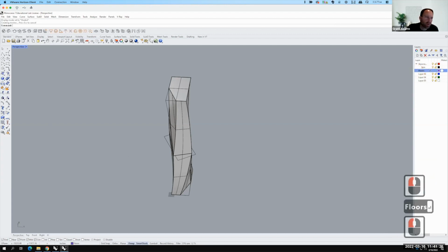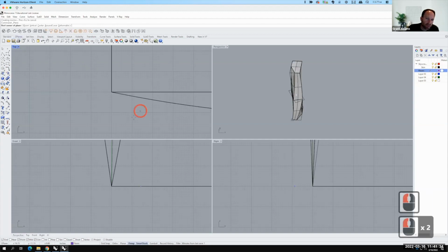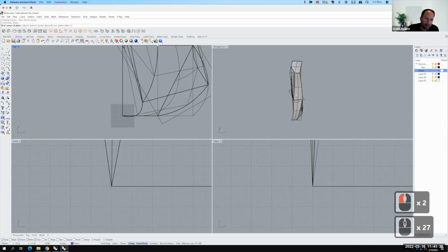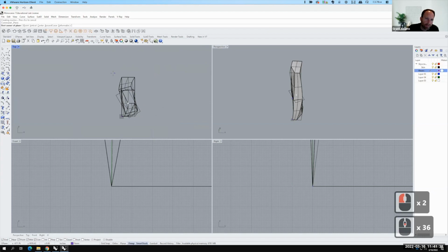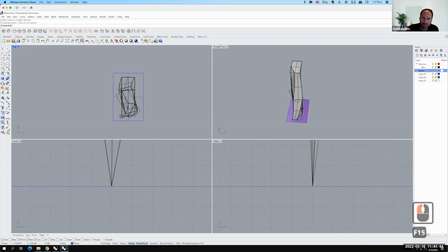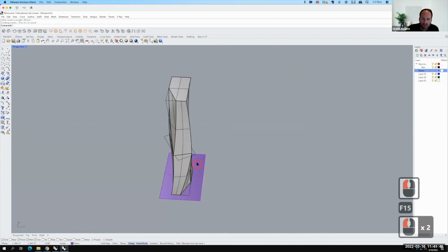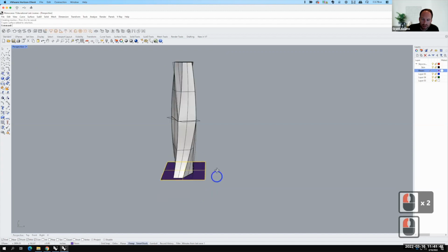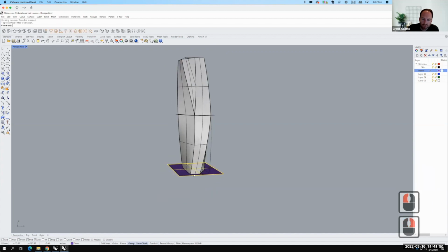And I'm going to draw a rectangular surface. I can use the corner to corner, larger than my building. It's probably easiest to do it if we were looking down on my building. And we want to make sure that it's larger than my whole building. Not too big, but larger than my whole building. There it is. So this surface, because this building's 600 feet tall, the first floor is going to be up 24 feet. So floor to floor of 24 feet.